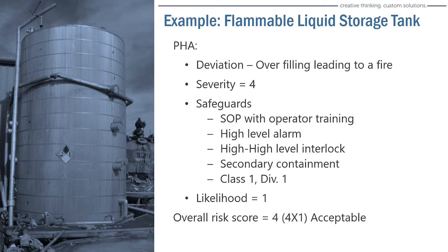How often will the operator miss closing the valve? How often will that high-level alarm fail? How often will that high-level interlock not work? What about secondary containment? And what if there was an error in PMs and all of a sudden a non-intrinsically safe piece of equipment got put into the vicinity of that tank? That's what LOPA does. LOPA takes those things that we qualitatively assess and actually puts some numbers to them, so you can come up with a semi-quantitative risk score. Now I'll talk about how that's all done.